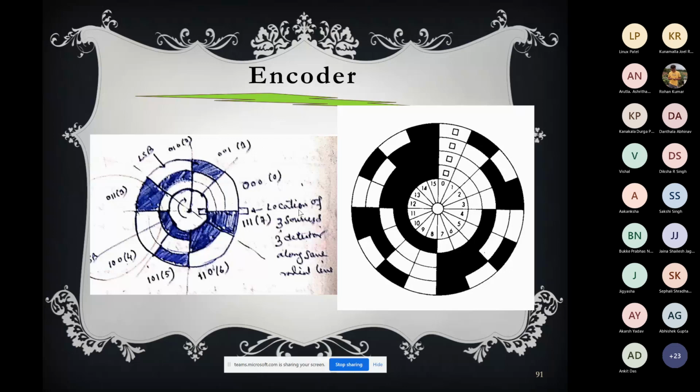Now, if we think about the encoder, it is a digital sensor. If we use the encoder, we don't need to have an A to D converter. Directly we can feed it to the computer. Now, as we discussed, there are two types of encoder. One is the shaft encoder or rotary encoder, and the other is the linear encoder. Among these two again, each can be divided into absolute encoder and incremental encoder. And based on the operating principle, encoders can also be divided into optical encoder and magnetic encoder. So I said that among these, the optical encoder is the most popular.